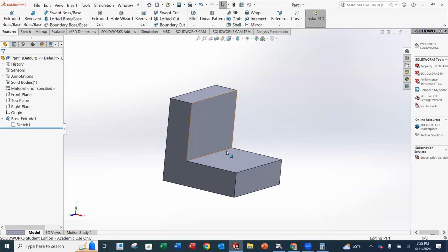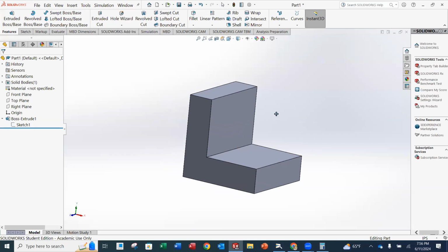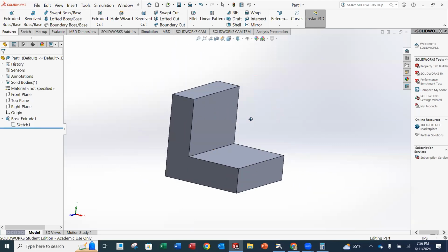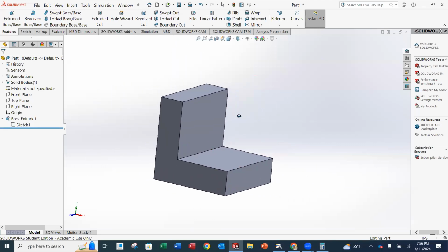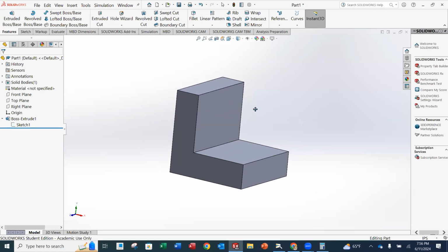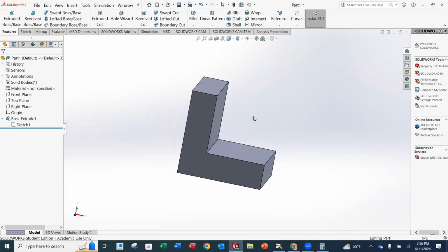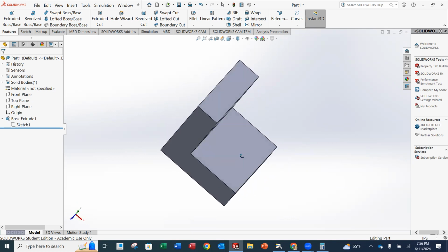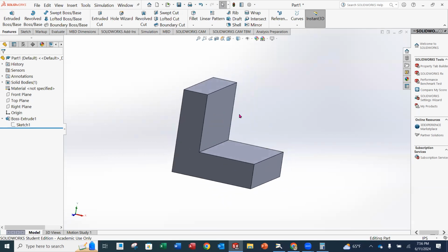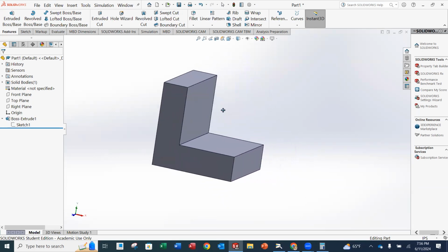The other thing you can do is pan, and pan is where you just move it left, right, up, down. You're going to hit and hold the control key, and you're going to depress your middle mouse button. You hold it and go up, down, left, right, and that's just a pan. Okay. So if you don't hit the control key, it's going to rotate. If you have the control key and you move, it's going to be a pan.